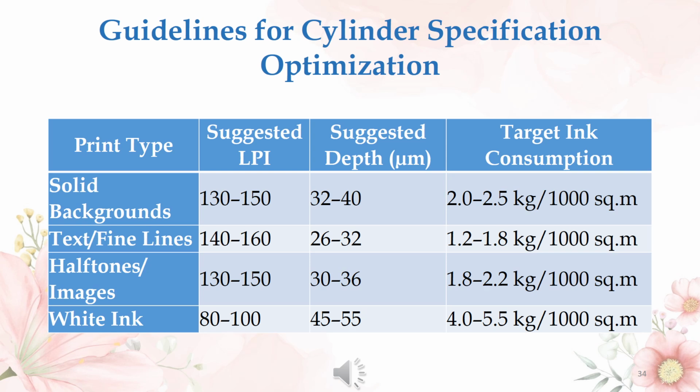Here are the guidelines for cylinder specification optimization. For different print types, the suggested LPI range and suggested cell depth range are given.